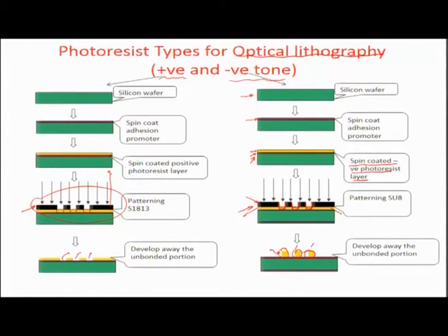Then there is yet another kind of lithography which is done by this mask going away quite a bit of distance and being projected through a properly guided optical system, so that one ensures that there is no resolution loss or no change in the overall sizes and dimensions of the projections. There can be lensing systems which guide the light from a longer distance, and if the mask is far away, the advantage is that every time you have a wafer, you can, without removing the mask, do exposure and go for the next wafer. So, these are high yield processes used by the industry, and we call them projection lithography.